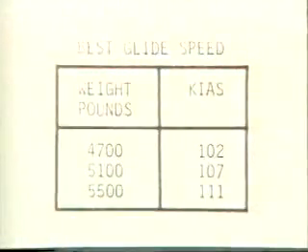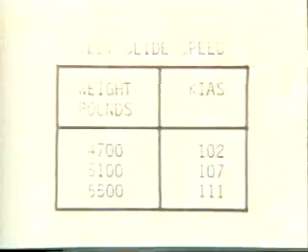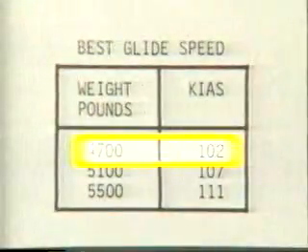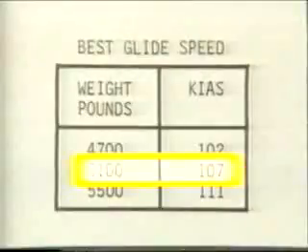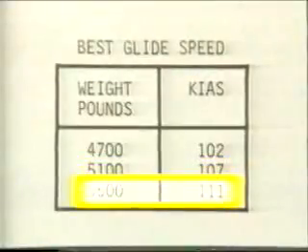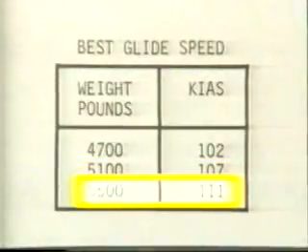Therefore, small deviations from the optimum coefficient of lift will not cause a drastic reduction of the lift-to-drag and glide ratio. On an aircraft with a wide range of weight possibilities, the manufacturer might list more than one speed. This is because as weight increases, the speed required to maintain the LD max angle of attack also increases.